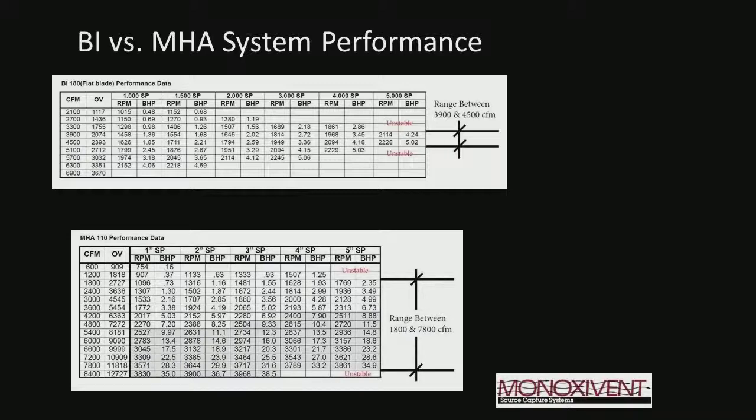When you look at it that way, are we really, truly saving energy? Are we saving money? Are we getting what we think we're going to get? If we have to put a 40 horsepower motor on it, maybe it's really not the way to go to do a VFD. So those are some things that you really need to consider when you're doing this.